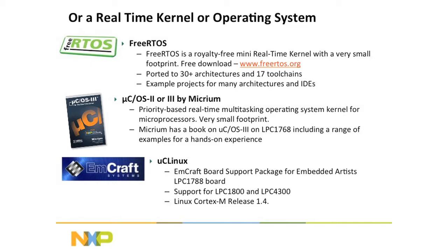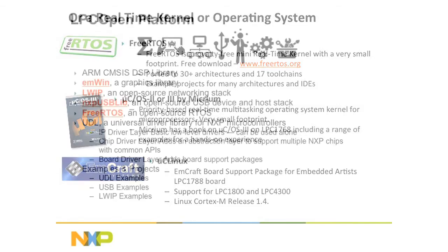But FreeRTOS is right now the main one that we support. There's also Linux support in the form of uClinux, which is basically Linux for microcontrollers that do not have an MMU. We have ports of that for the LPC1800 and LPC4300 series parts up on LPCware, if you want to experiment with that.